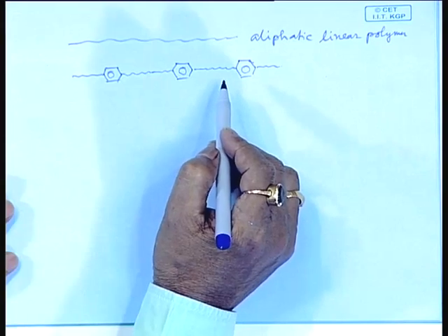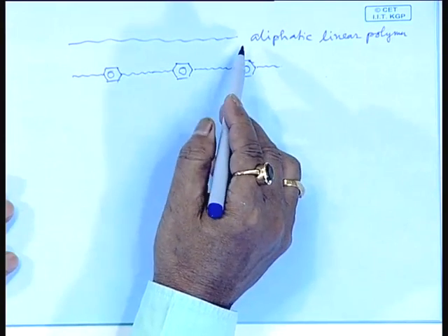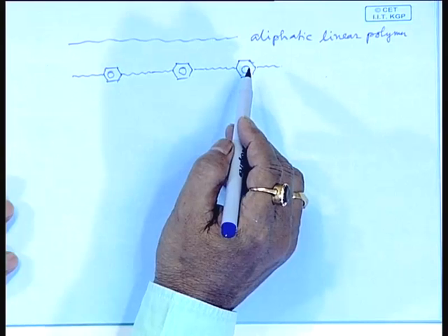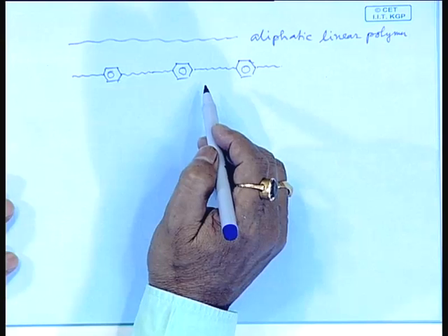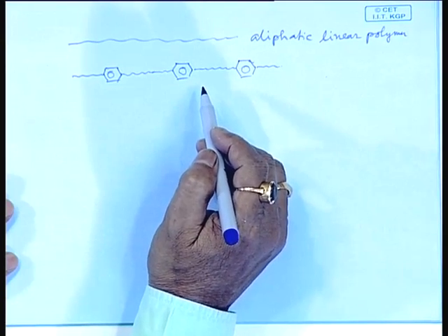But at the same time, if we move like this, we can achieve a polymer with high brittleness. So, you have to think of the impact properties also, you have to keep in mind the impact characteristic also. We need a strong polymer as well as a high impact polymer, as well as a thermally stable polymer, as well as we must see that it becomes easily processable. That means you have to think of the processability, the temperature at which it melts.